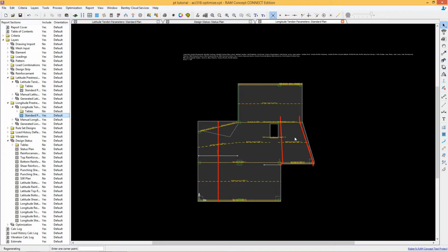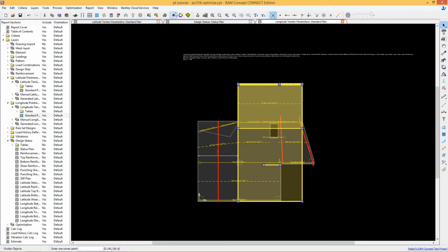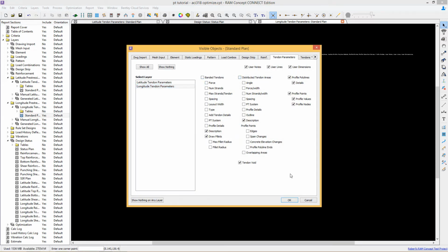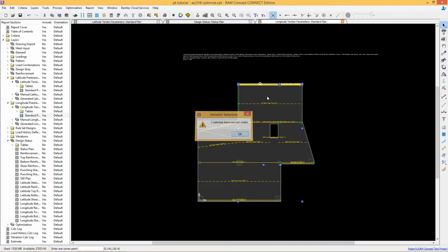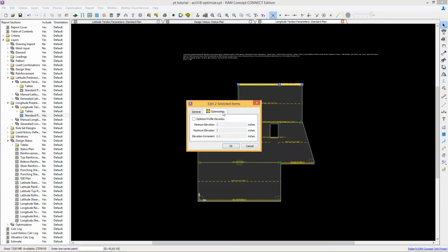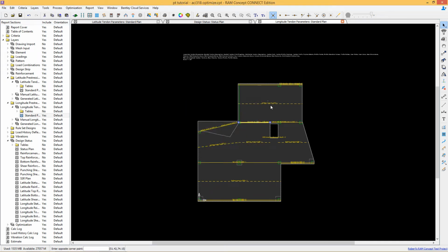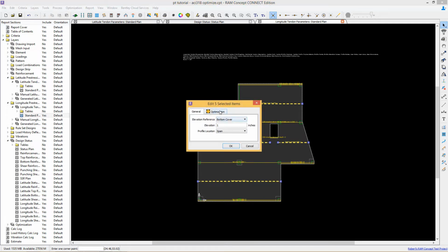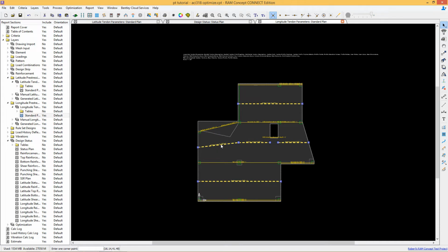And we'll do something similar in the other direction. Again, if we look at the end elevations and the high point elevations, we've deselected all of those, so those will not be optimized, but we do want to vary the drapes for these low point elevations. And so again, we'll use 1 to 7 to give it the maximum space to explore.